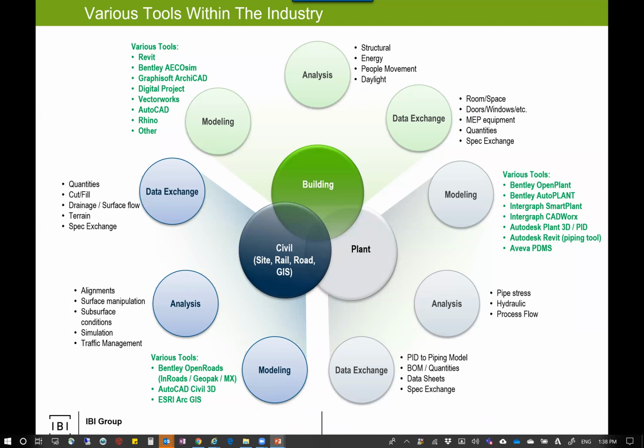And why is that important? Again, the connection to the P&IDs is very important, but I also want to do a pipe stress analysis. And I run an application saying, if I have a plastic pipe, I'm going to run 100 PSI of pressurized something through it. It might be gas, and it might have a temperature of 30 degrees Celsius. I want something to tell me, first of all, whether it'll work or when it will fail. Can it sustain the temperature? Do I need to insulate it? All those questions. Building apps are not going to give me that.